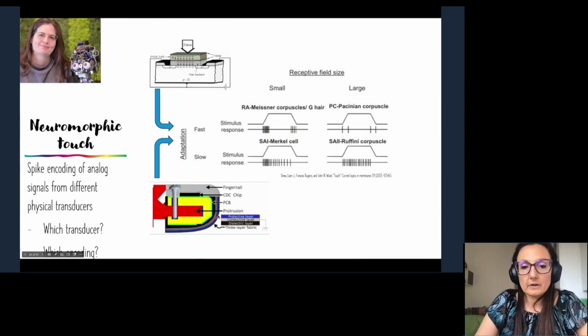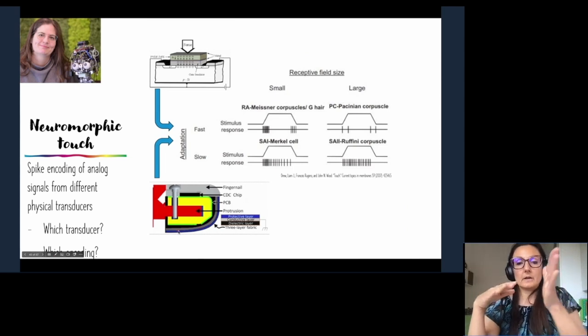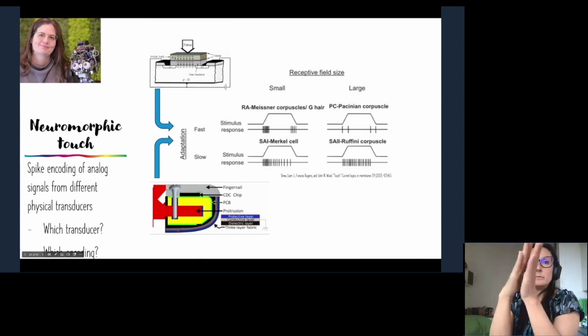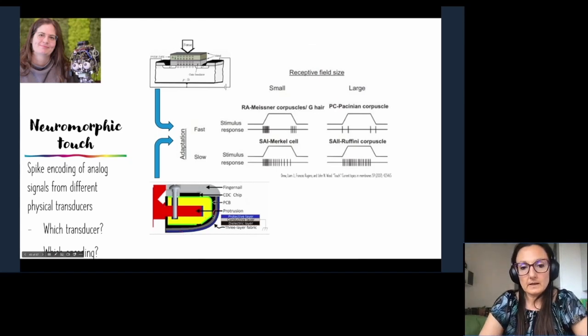This is the cross-section of a fingertip of the iCub robot, with a fingernail, with a chip that does the acquisition. Basically, what you have here is this layer of skin where you have two plates of the capacitor, and in between a dielectric. So when you press, the dielectric changes size, and so the capacitance changes. And you have multiple of these on the fingertip. You can use this, for example, for the slow type of encoding, the slow adaptive.